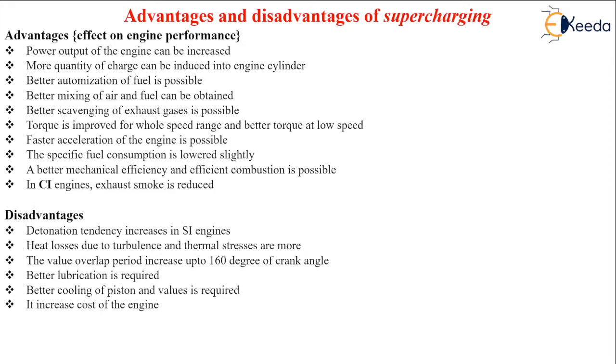Then better atomization of fuel is possible. Why is this? Let us consider the fuel to be at atmospheric pressure, and the air compressed to a degree greater than atmospheric pressure. Then the pressure head between the compressed air and the fuel at atmospheric pressure will be higher. As a result, the expansion process of the fuel will be more efficient, and it will be easily converted into atomized particles. And when the fuel is atomized properly, better mixing of air and fuel can be obtained. This is the next advantage.